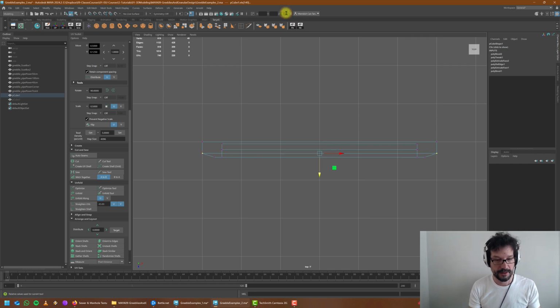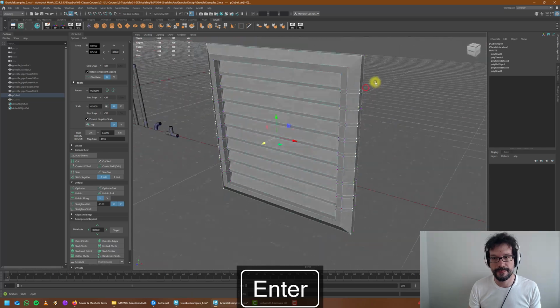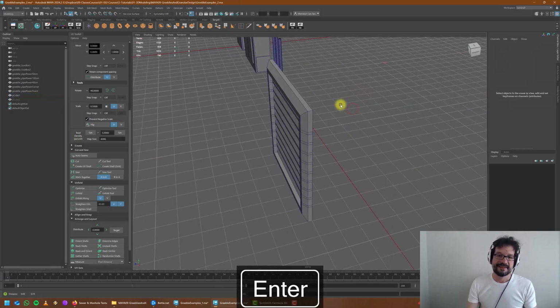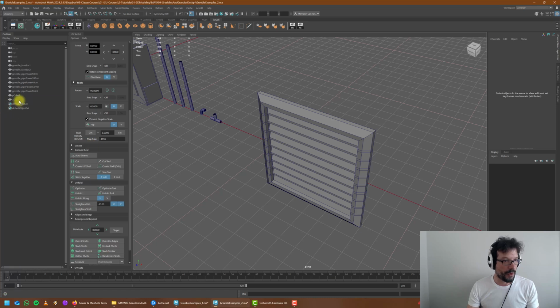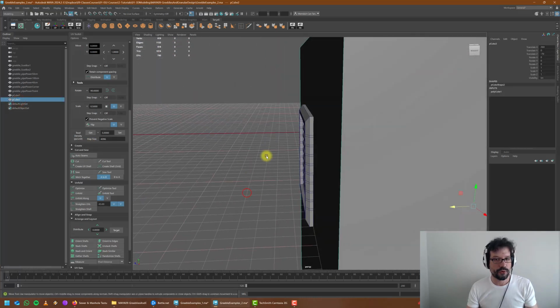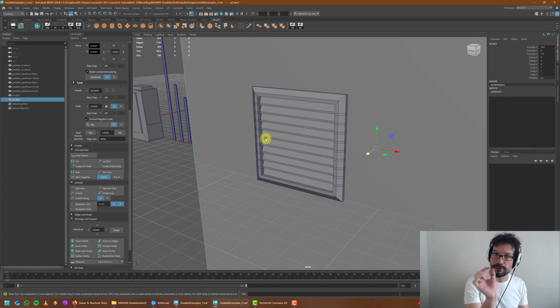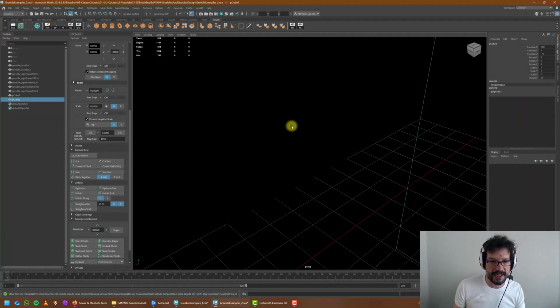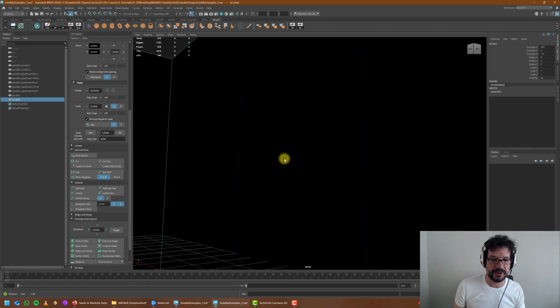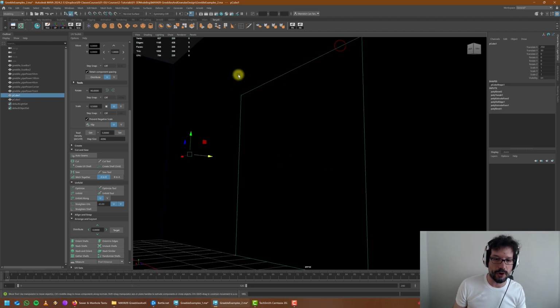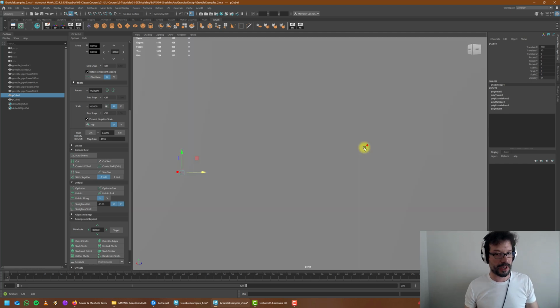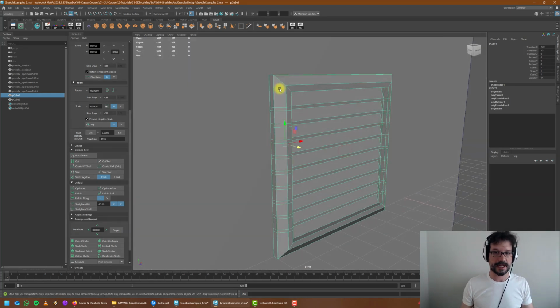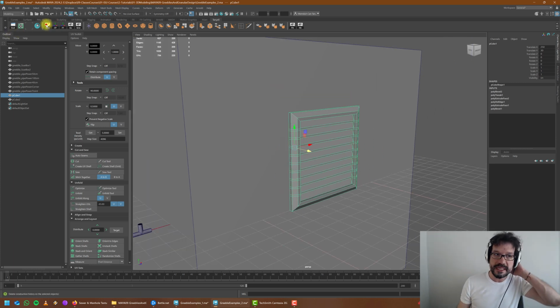Now let's slightly modify this. So this is maybe 1. Now this ventilation shaft will stick out from the wall as a more robust object. It was very thin beforehand, but right now it is sticking out more. As you can see, it is not colliding with the object. The only thing doing any collision is its outline, which isn't a problem for us. Previously, the wall entirely collided with the openings on the grate itself. So be careful with these kinds of situations.